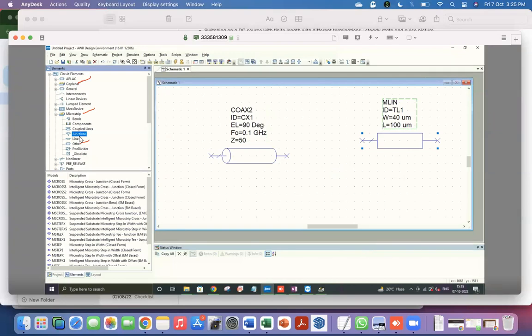So it's modeling how a microstrip line will come in and split into two. So it gives a physical model for that. Then there are coupled lines, which is exactly what we're looking at. So two lines next to each other. The way one uses them is exactly the same as what I'm going to show you right now. Okay. So I went to the lines and I used this MLIN microstrip closed line form.